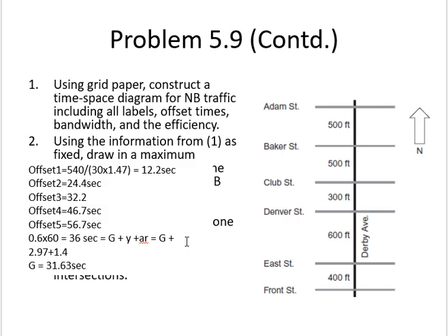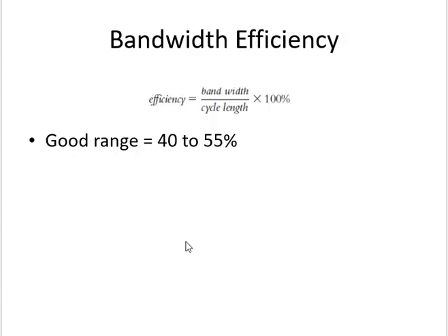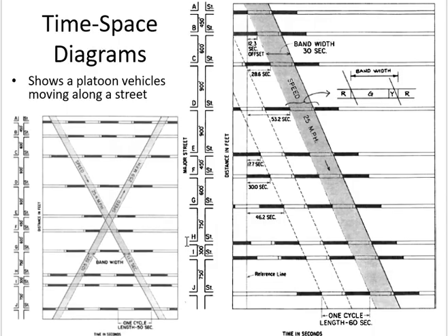So the first part is just plot this and make the first line. If it is one-way progression, you can make the second line from the yellow, no problem. You have the whole green and yellow for your bandwidth. One-way progression done. But if it is two-way progression, then you have to complete the graph like this, and then you will see the gap in the graph in which both lines can continue together.